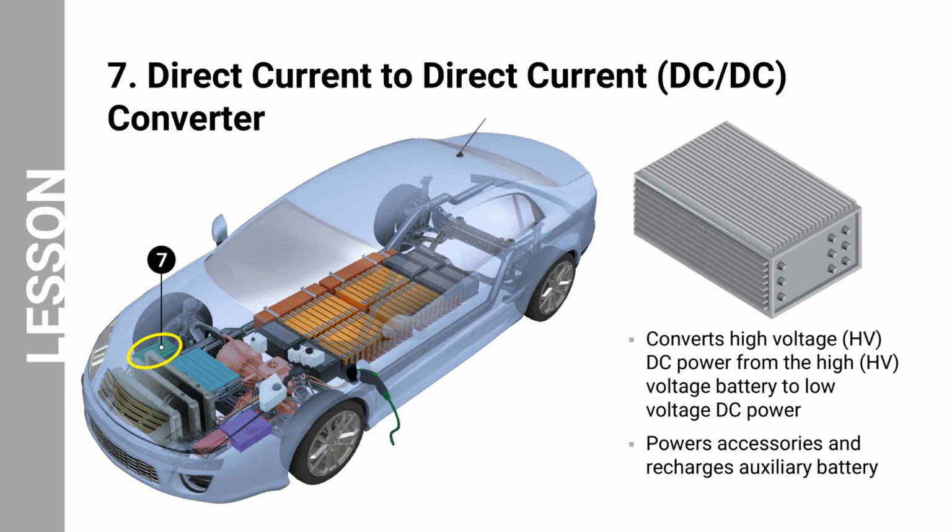This includes the motor, the inverter, the electronics controller, and the auxiliary systems such as the lights, the heating, ventilation, air conditioning, abbreviated as HVAC system, and the infotainment system. While the DC to DC converters can be based on several different designs, the underlying function remains the same. The batteries of a BEV typically output several hundred volts of DC. However, the electric components inside the vehicle vary in their voltage requirements, with most running on a much lower voltage. This includes the radio, dashboard readouts, air conditioning, and inbuilt computers and displays.